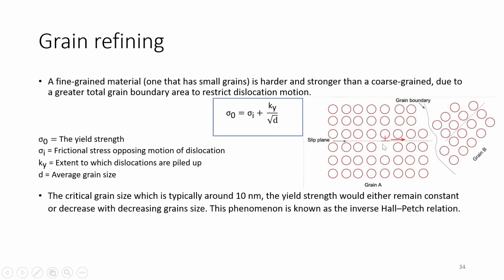Here, this laser point is visible, right? So this one nuclei and this one nuclei, these two are growing, and at this particular place, they will stop. So they can't grow into another nuclei, right? After this, there will be this barrier, this particular point, this grain boundary, which won't have this type of crystal structure. So these will be forming during the casting of the material.